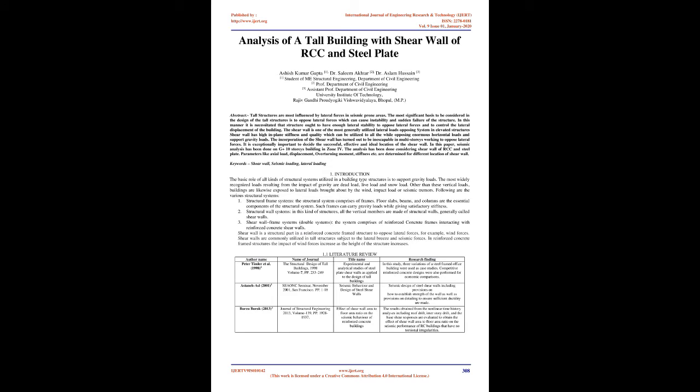Shear wall is a structural part in a reinforced concrete framed structure to oppose lateral forces, for example, wind forces. Shear walls are commonly utilized in tall structures subject to lateral wind and seismic forces. In reinforced concrete framed structures, the impact of wind forces increases as the height of the structure increases.